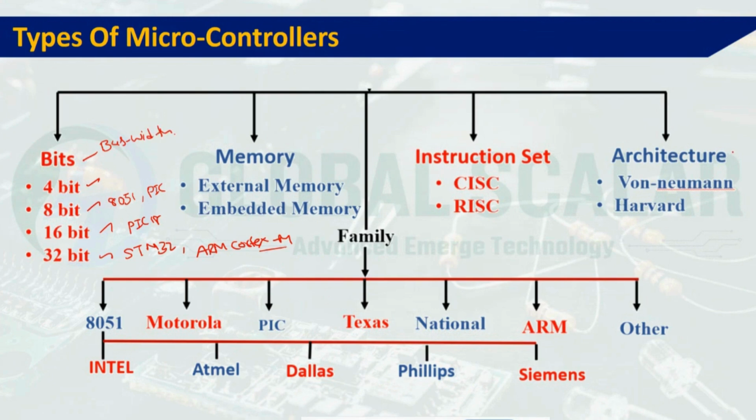Next, part of the hardware is that the microcontroller we choose should be considered architecture-wise: it can be Harvard architecture or Von Neumann architecture. What is the hardware? Specifically, it is the memory storage and the signal pathway. In Harvard architecture, there is a separate signal pathway for instructions and data.